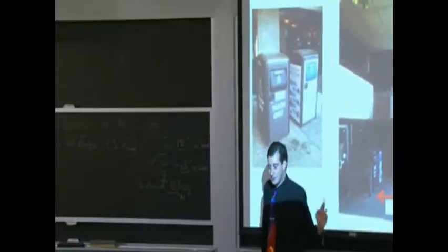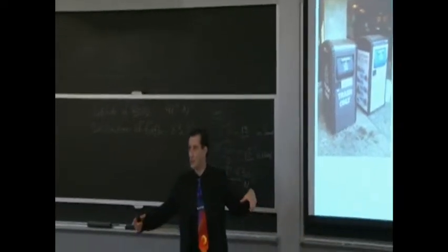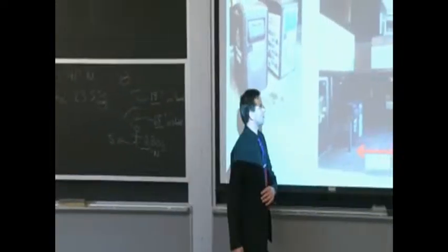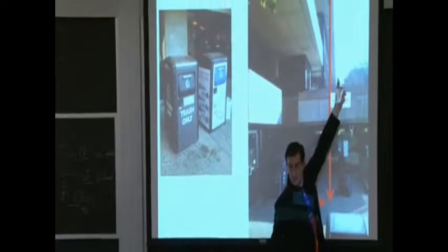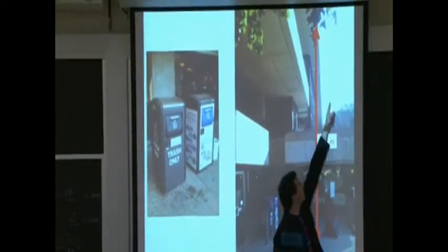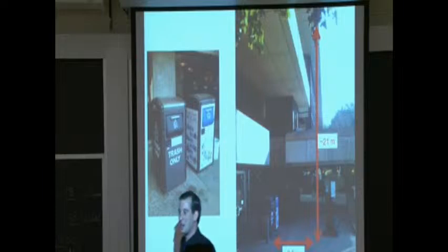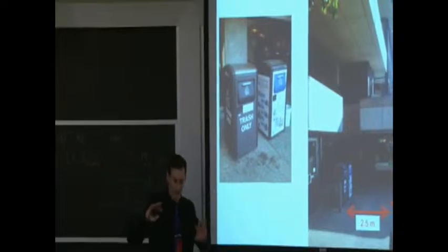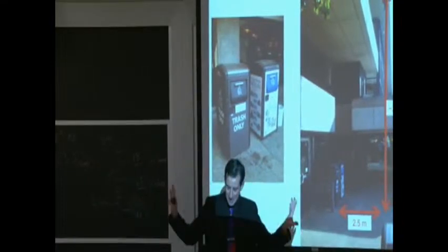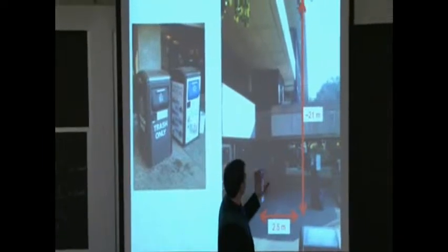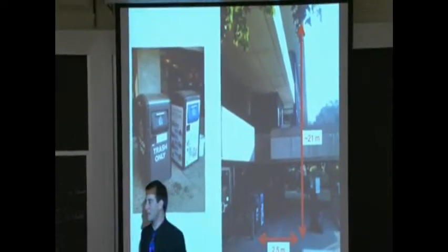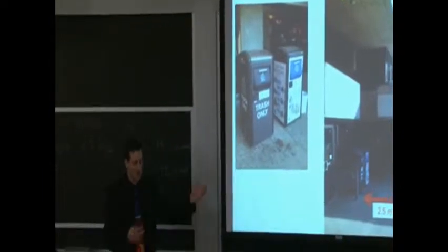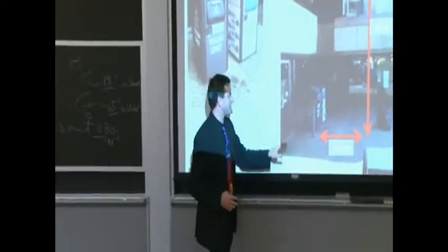That's not a problem for this particular trash collector, since those panels are way oversized for the amount of energy that the trash collector actually needs. And there is a fair amount of what we call diffuse sunlight, meaning sunlight being scattered off of other things. That's why this portion of the image looks white. It wouldn't look white if there was no diffuse scatter. It would look black, pitch black, if there was nothing to scatter the light off. Like in outer space, there's nothing to scatter. That's why it looks like a black night. But instead, there's a large amount of diffuse light. There is still some sunlight reaching it, and since the panels are way oversized and the system is over-engineered, it still manages to acquire enough energy to compact the trash, and it doesn't have a catastrophic stop.